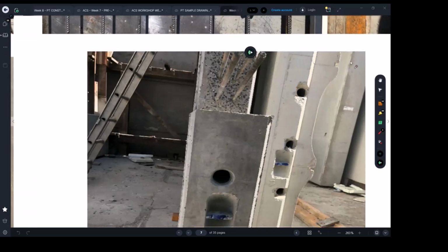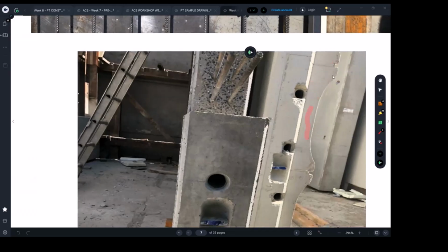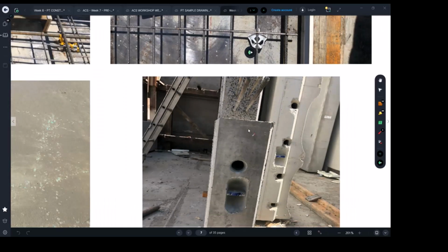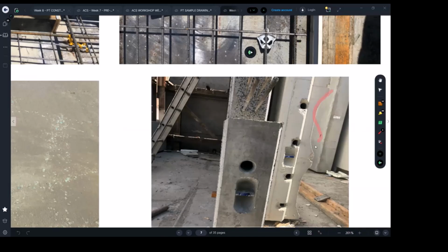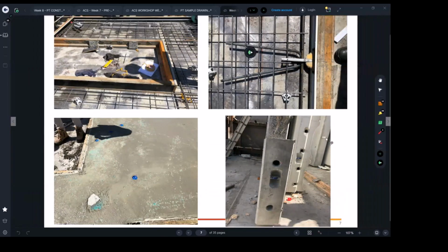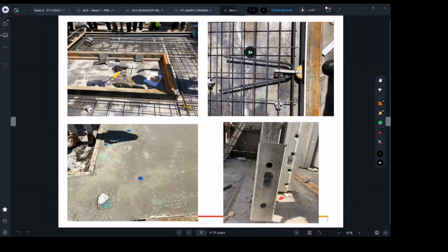Usually they make those features non-structural. They will have their own reinforcement and detailing, but they are not structural. The structural part, which will be carrying the forces, actions and stresses, is here, within this 150 thick. It looks like this panel has some special features because they're putting it in the facade and want that nice look. But not all of them are going to be like this. It's maybe only the ones facing the street where they want this special look. So yes, these things can be extra.